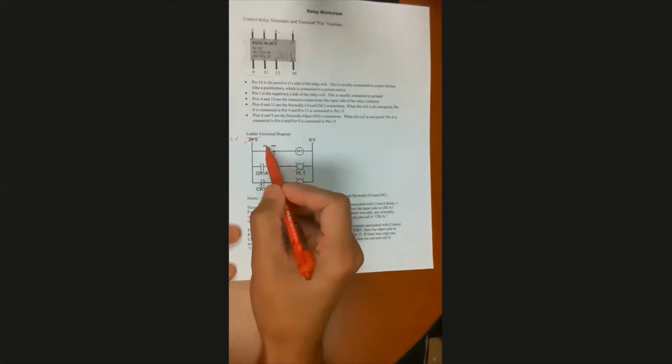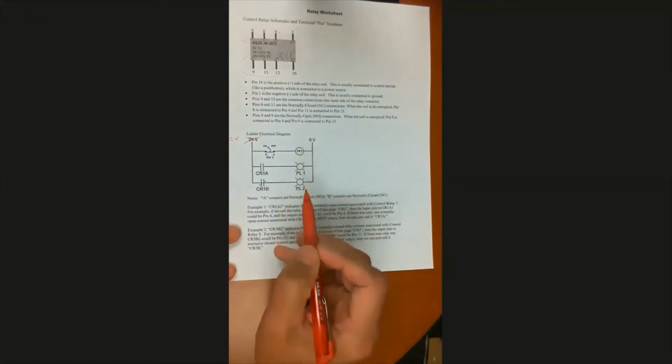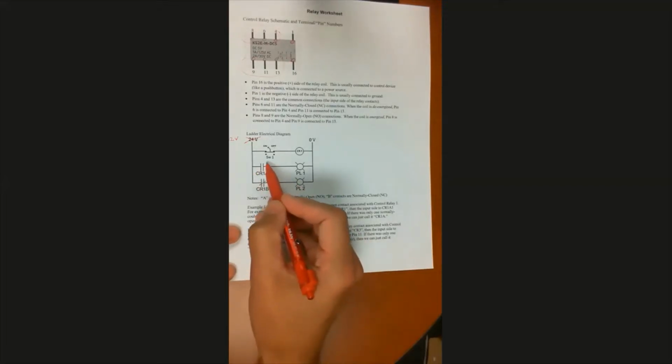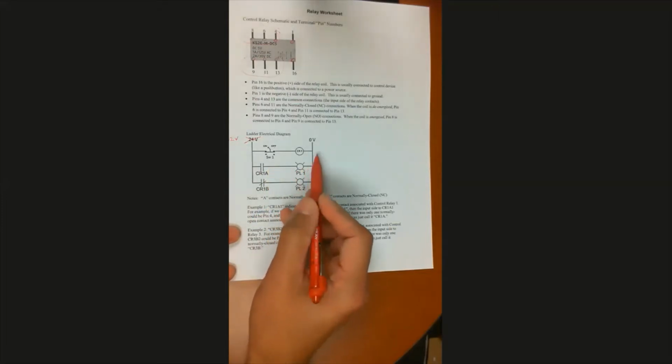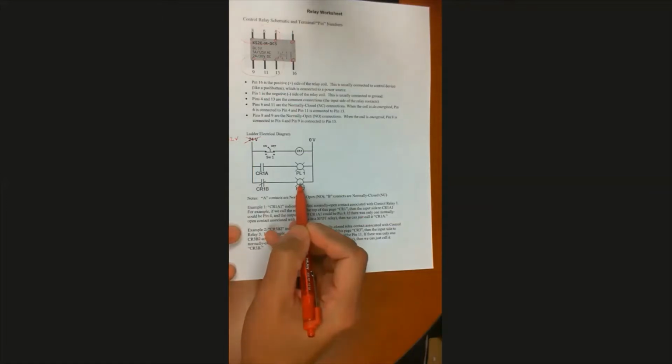Then when it's on, when the selector switch is in the on position, then our coil of control relay 1 energizes. And remember, the plunger moves inside the solenoid, which changes the position of the switch. So now all of our normally open contacts close and all our normally closed contacts open. So now this one closes, which means I have continuity through it, which means PL1 energizes. And this normally closed contact opens, and so I don't have continuity through here, so PL2 turns off.